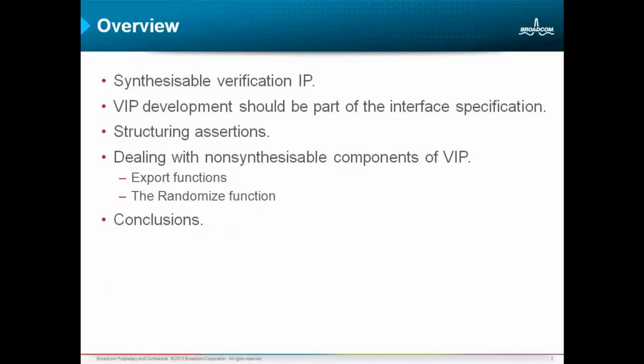What I want to talk about is how I've been using formal verification in the design of our interfaces. Some quite low-level interfaces. I don't know how many people are aware, but Broadcom's always been very big on synthesizable verification IP, mainly because we use it a lot with emulation. And one of the advantages of having synthesizable verification IP is it also works with the formal tools.